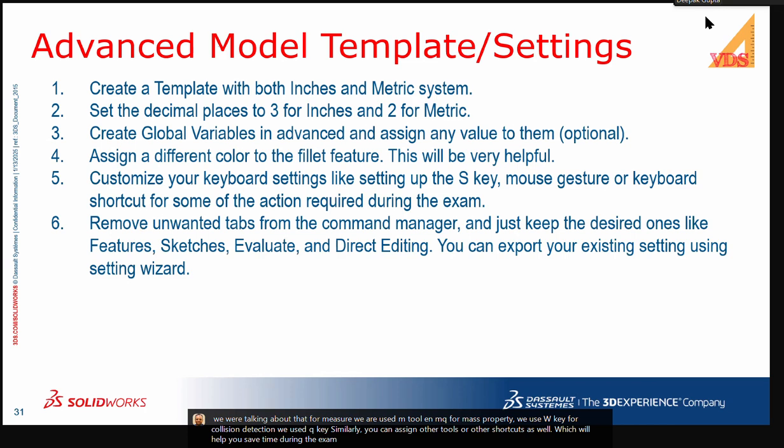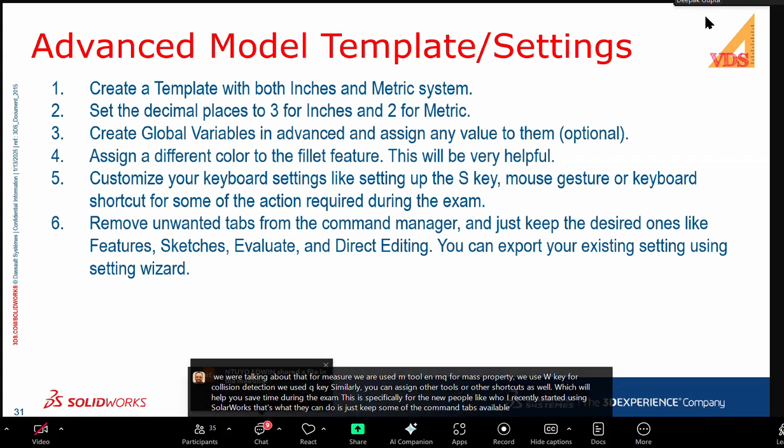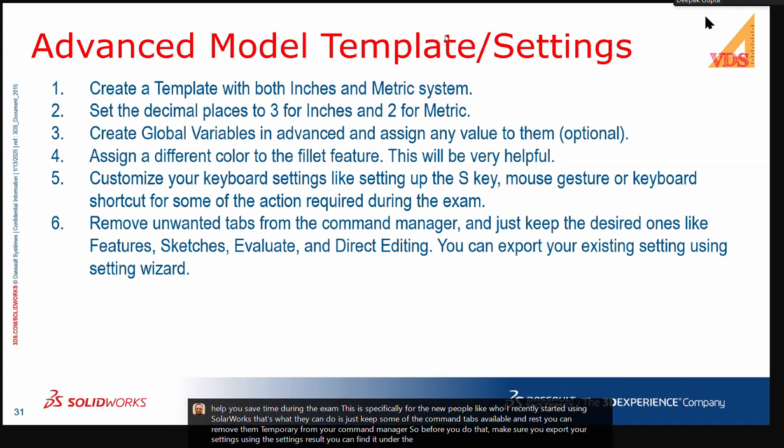This is specifically for new people who recently started using SolidWorks. What they can do is keep some of the command tabs available, and the rest you can remove temporarily from your command manager, right? So before you do that, make sure you export your settings using the settings wizard. You can find it under the tools settings wizard.